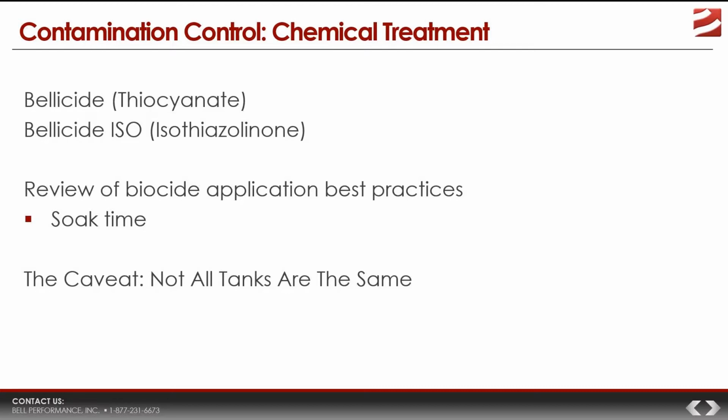In broad terms, it's got excellent broad spectrum action, which means it kills a lot of different microbes. And it partitions well across the fuel-water interface. Basically that means it can dissolve in the fuel, and then move into the water phase, and keep killing, and that's important.